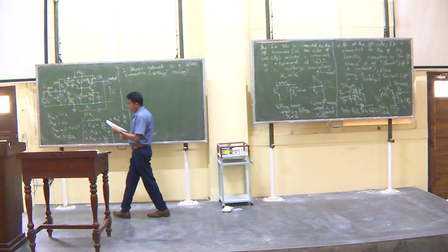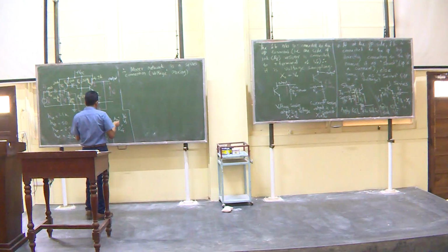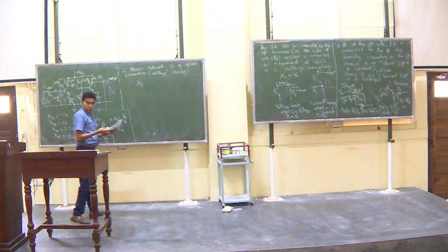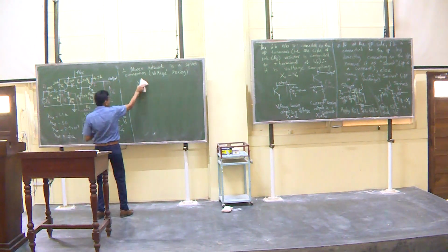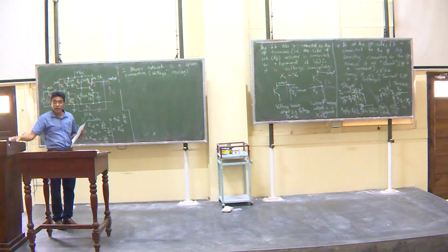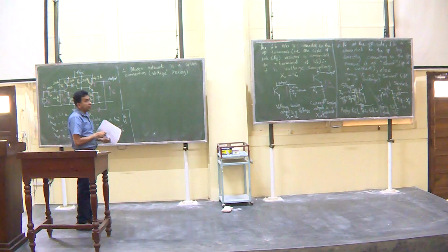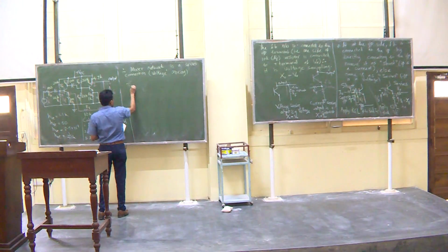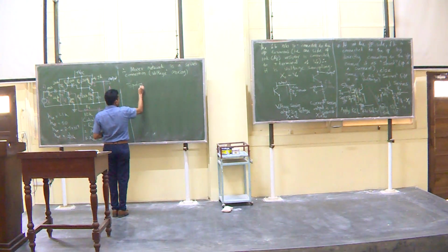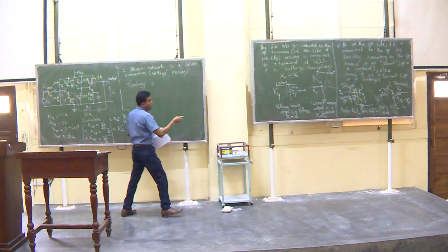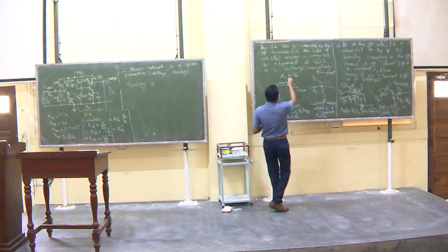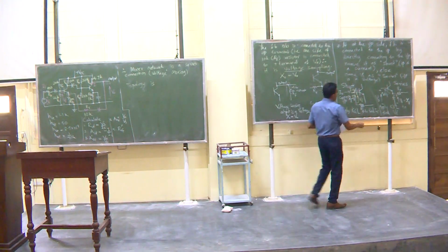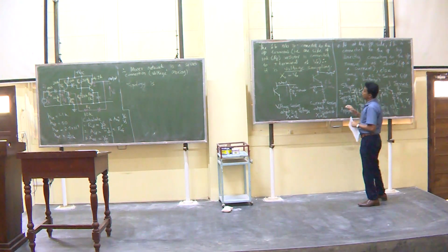Right. So, therefore, what is X f? Before that, we will identify the topology. Now, with this we have the two things necessary to identify the topology. So, therefore, topology is voltage series, right.